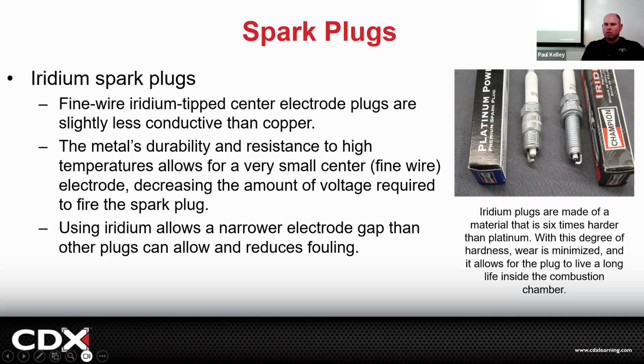If you take them out and they don't look super fouled, like we looked at mostly during engines, the different types of fouling of spark plugs, if they look pretty good, we're good to go. We don't need to change them very often. If you do change them, it's mostly due to the miles. If your coil goes bad and doesn't fire, the plug won't get hot because there'll be no combustion. It can be fouled up and dirty. Then you may change the spark plug, right?